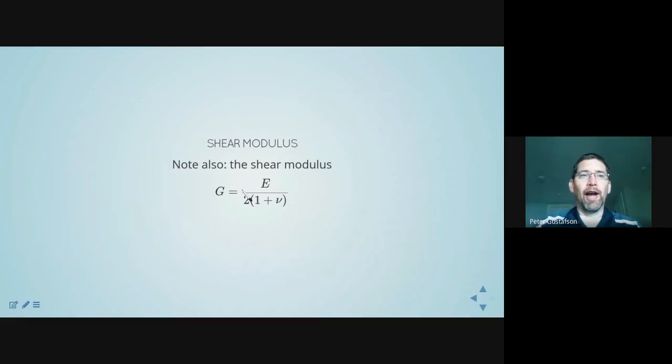Inconel, all the high temperature alloys that we sometimes use in supersonic flight vehicles, I should say almost all of them, behave as isotropic materials. So if you know the Poisson's ratio and you know the Young's modulus, then you have a sufficient amount of information to describe at least the linear portion of the material's stress-strain response.